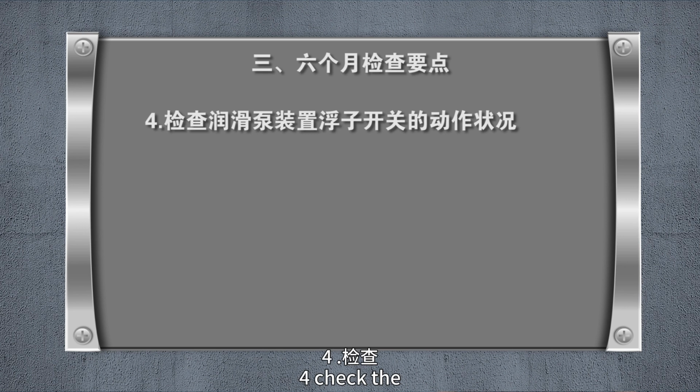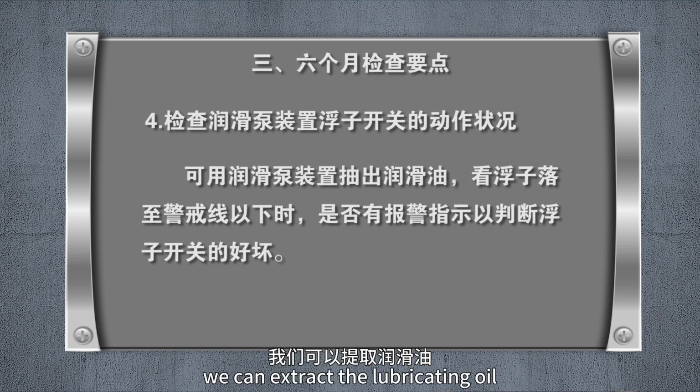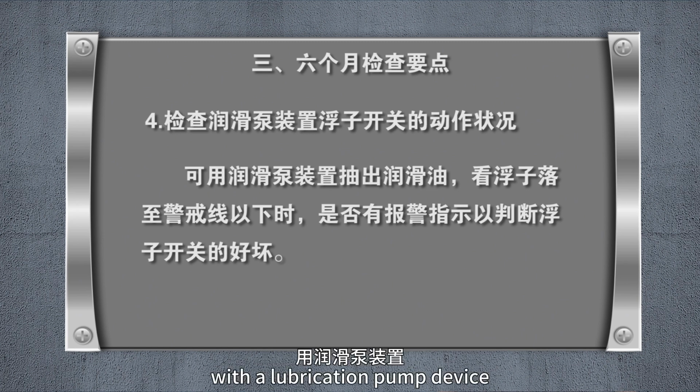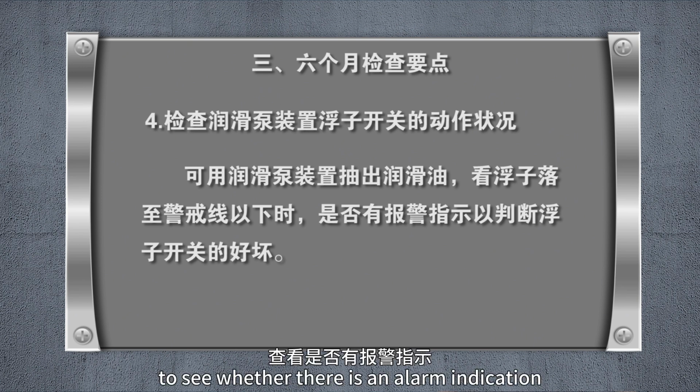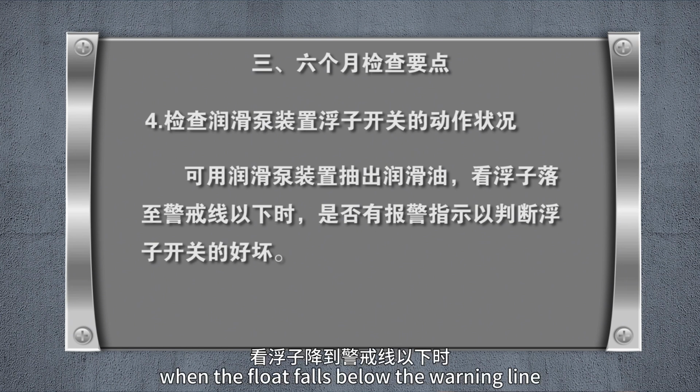4. Check the operation status of the float switch of the lubrication pump device. We can extract the lubricating oil with a lubrication pump device to see whether there is an alarm indication to determine the quality of the float switch when the float falls below the warning line.